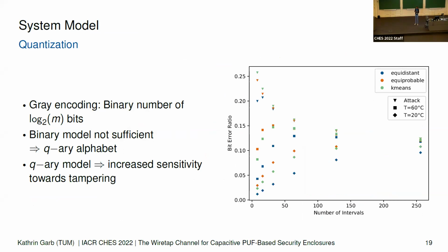If the error gets too large, you will have this effect, because you no longer have 1 bit of change. So you have to consider how you quantize it. How do you optimize your quantization? Can you optimize the post-processing steps? Could you maybe do the normalization in hardware?